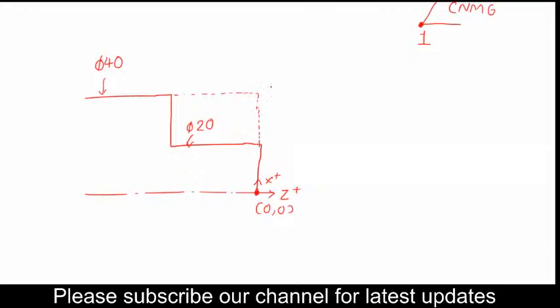Okay, so we have to bring the tool down from that far location to the nearest location, and I'm just drawing the tool. Let me give that point number 2. So what we have to write in order to move to point number 2 is G0, which is rapid linear interpolation: G0 X45 Z2.